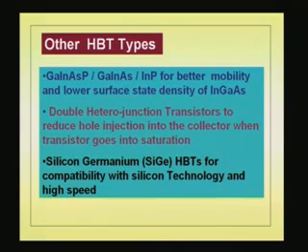Now, the other types of HBTs are gallium indium arsenic phosphide, that is a quaternary on a ternary gallium indium arsenide on a binary compound. Now, here all these are lattice matched, that is gallium indium arsenide matches with gallium indium phosphide. You add a little bit of phosphorus to that, okay, the band gap goes closer to indium phosphide. In fact, I just wanted to put that diagram.